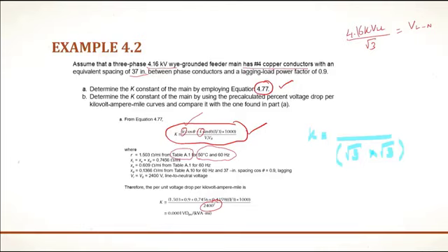So this will give us whatever is the original value of K, that will be divided by 3, as we are having under root 3 square in the denominator. So both of these voltages are being increased under root 3 times. Correspondingly, the value of K is being reduced to 1/3.